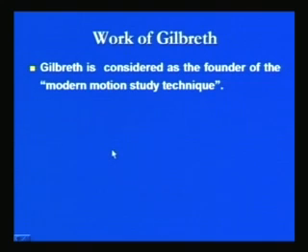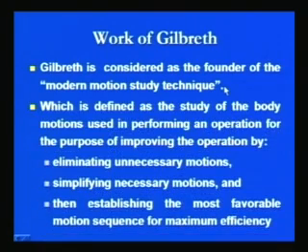Another person who has worked significantly is Mr. Gilbreth. He is considered as a founder of the modern motion study technique, and this is defined as a study of the body motions used in performing an operation for the purpose of improving the operation, and it considers the movement of the different body parts while carrying out the job, so that the job can be improved either by eliminating unnecessary motions, simplifying the necessary motions required for carrying out the job, and so as to establish the most favorable sequence of motions for achieving the maximum efficiency.